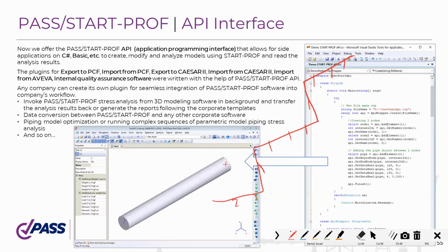The idea is that you need to remove one of the supports and run analysis, and analysis results should satisfy the code requirements. All the nozzle loads, all the stresses in this piping system must satisfy code requirements. After that, you return the support and remove another support and run analysis again, and so on.